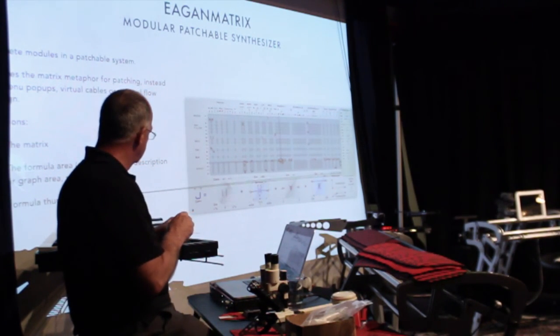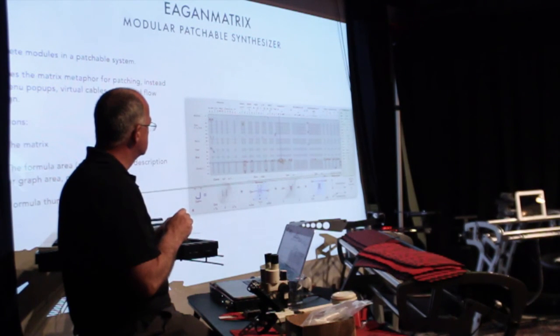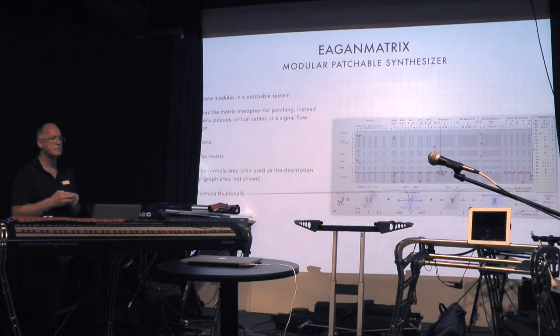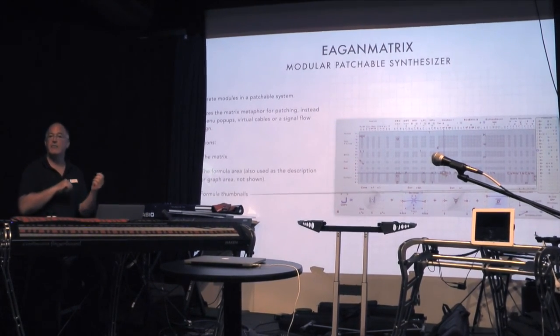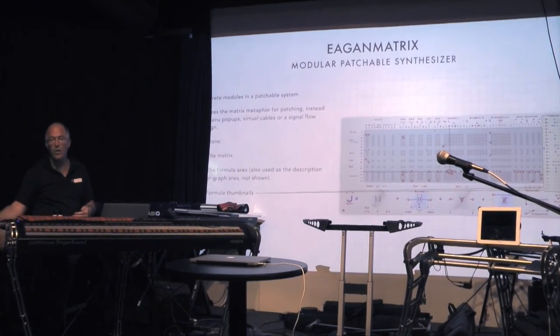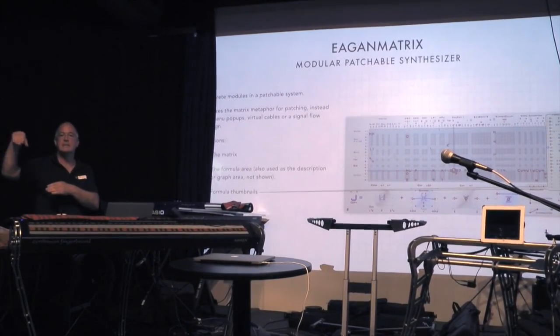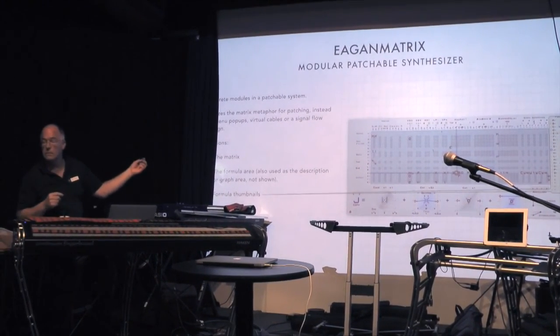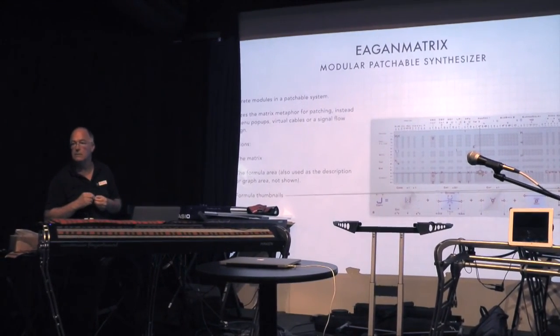I just tell people, if you want to use Kyma, just stay in Kyma. It really works. It has a lot of capabilities, and to try to port to another system and then say, oh, it's the same thing, I think is a bit of a pipe dream. And not only that, fixed point versus floating point, which was a real big deal for some of these biquad filters that we have, where the energy can go off the roof. There were certain things I could do in Kyma where you would just hit walls, whereas with this floating point system, we were realizing we were hampering ourselves. But just to be fair to Kyma, there are many things Kyma can do that this doesn't.